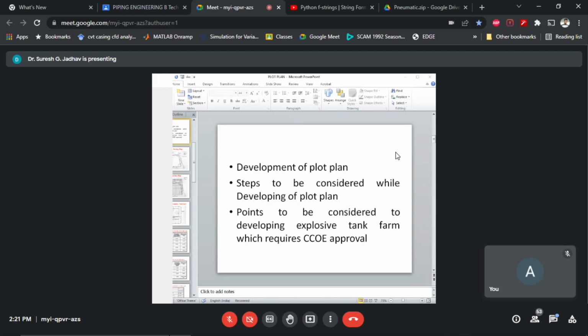It is better that the corner of the bund should be rounded and not at right angles, as it is difficult to extinguish a fire at a 90-degree angle corner because of the air compression effects. There should be a minimum of two access points on opposite sides of the bund to allow safe access or escape